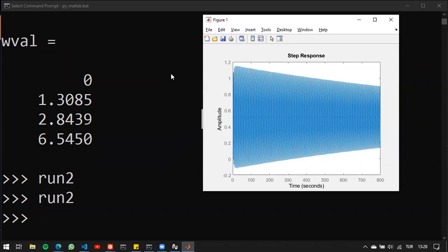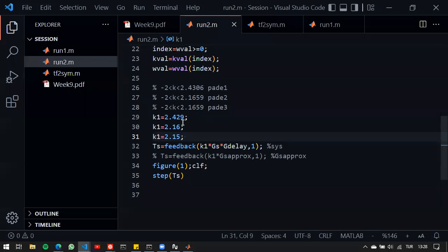And what can we say about a system that has delay in it, if we're using the Padé approximation? Well, we cannot say much, but we can say the following. Instead of giving you the stability interval, because it's not guaranteed, the approximation might be marginally stable, but the system might not be marginally stable. Therefore, if you use the Padé approximation, you get kind of the unstable region. You know that for values greater than 2.42, the system is definitely unstable. But you don't really know if it's between -2 and 2.42, if it's stable or not.